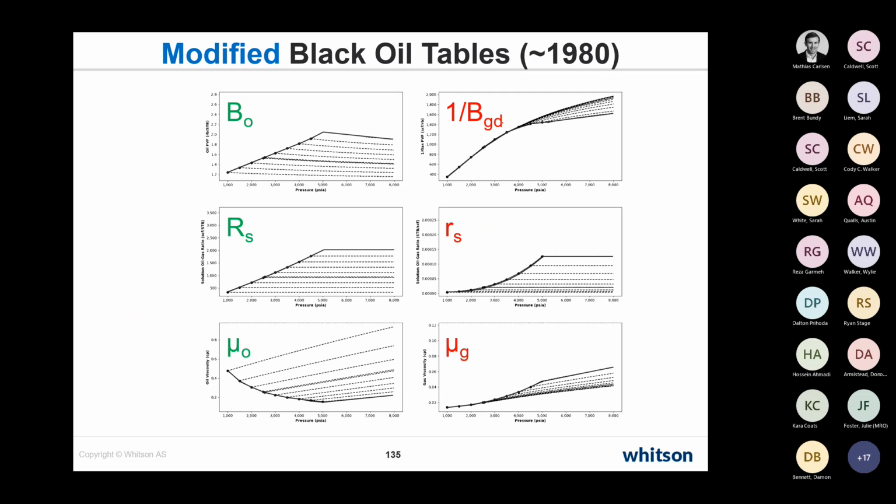And of course, for all these different undersaturated parts or all the saturated parts of the curve, you also will have an undersaturated part of the table that we just plotted on here. A little issue is if you have this table right here, and if you generate this table, it has around a solution GOR of 2000 there. But let's say after we created this table, my great friend here, Sarah Leames, for instance, says maybe the in situ representative GOR for this well is not 2000, it should be maybe 2500. The problem here, though, is that we would not have a composition with a solution GOR of 2500.